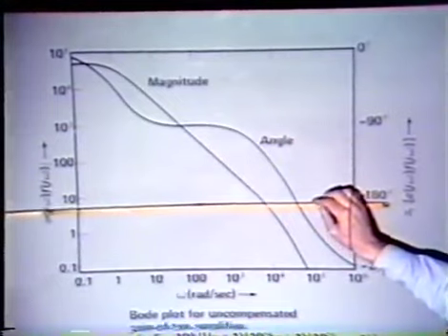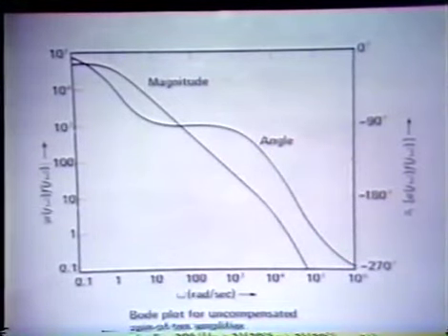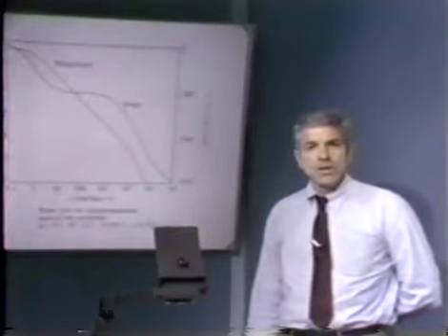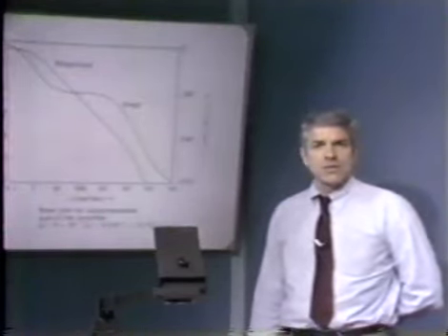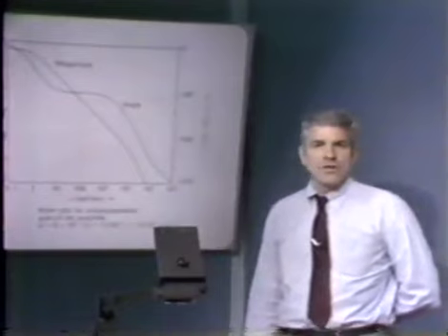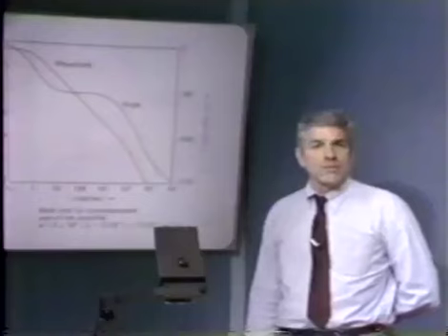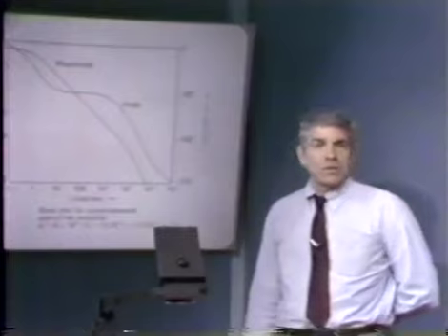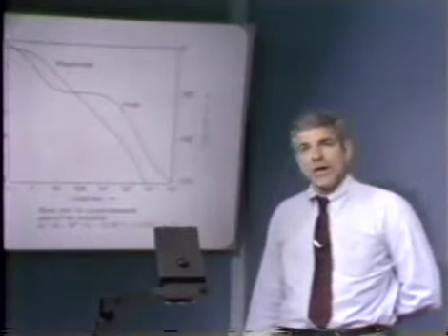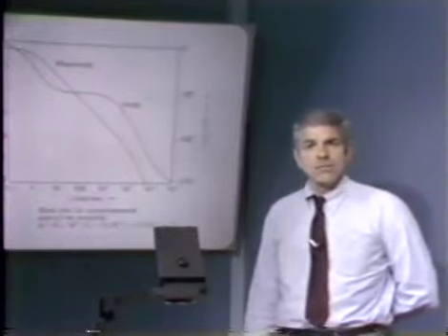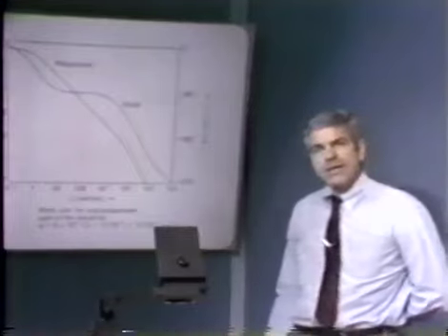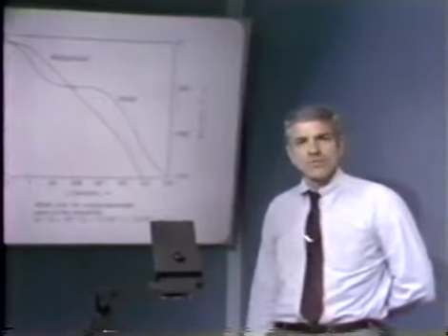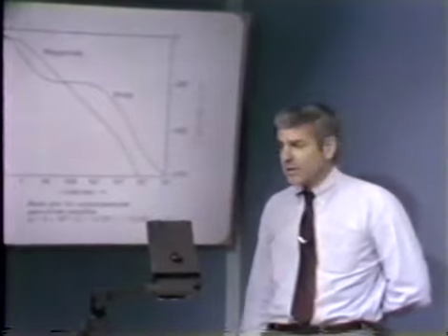These kinds of manipulations are very easily done in Bode plot form. You can get incredibly accurate answers. I mentioned one of the advantages of using Bode plots for actually determining numbers in compensation is that when you draw these things, you can get accuracies to really within the width of a pencil lead without much effort at all. And so we're able to get numbers that are at least good to 2 places with simply a piece of graph paper and a pencil. If we have a cheap hand calculator, we can do even better. But we're able to get far better results than usually the hardware justifies with this very simple graphical technique.